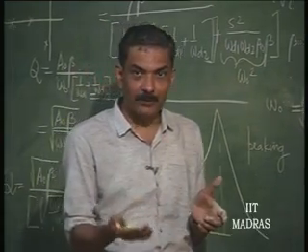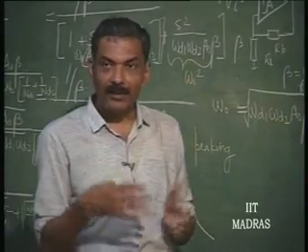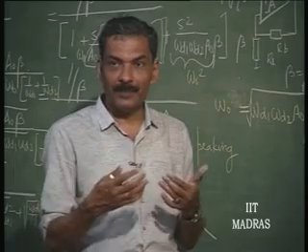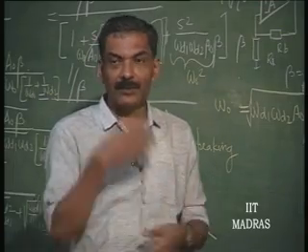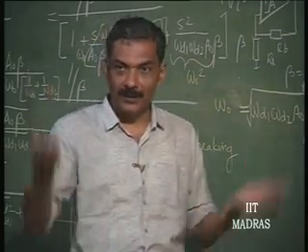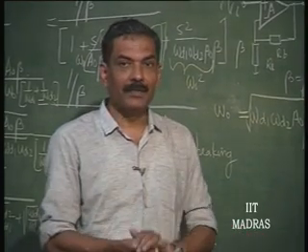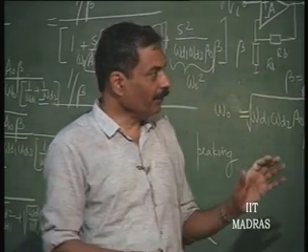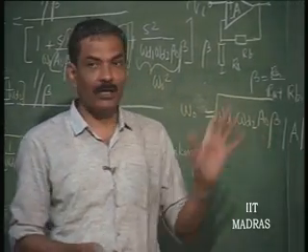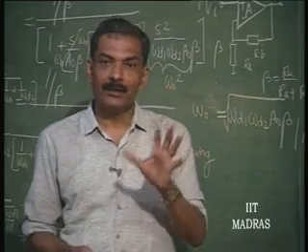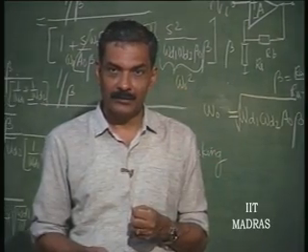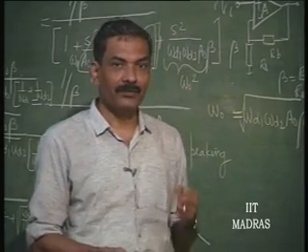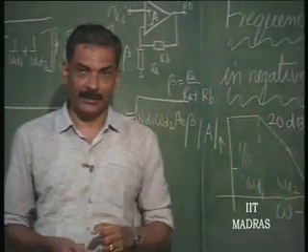At that point of time, if the loop gain is greater than 1, it will become unstable. There is regenerative positive feedback at that frequency, and therefore it will sustain oscillation. There will be a build up of oscillation at that frequency, and it will be a high frequency oscillation that you will see. So, a negative feedback amplifier which is oscillating is causing problems for us. We do not want this oscillation to take place. For that, we have to do what is called frequency compensation.